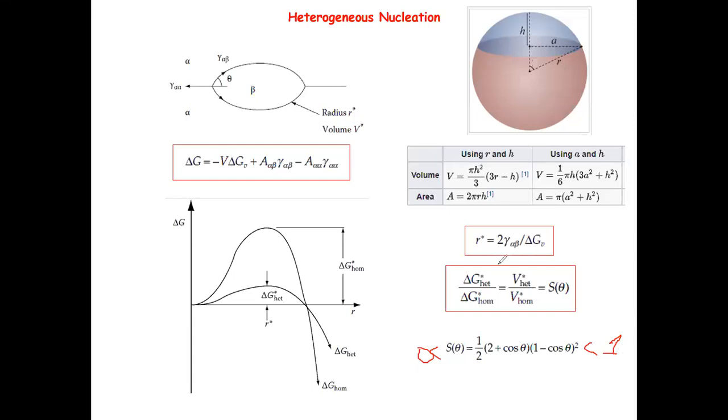So compared to the homogeneous nucleation, you're always going to get a reduction of the energy barrier for nucleation. But you also get a slightly different change of R star, which is the critical nucleus size, because in this case you don't have the extra term for the strain energy difference. If you remember, for homogeneous nucleation we have a strain energy term, which is also in the denominator, but here, because we're on the grain boundary, we wouldn't have this term. That's basically the difference. But anyway, the insights are basically the same as we had before.